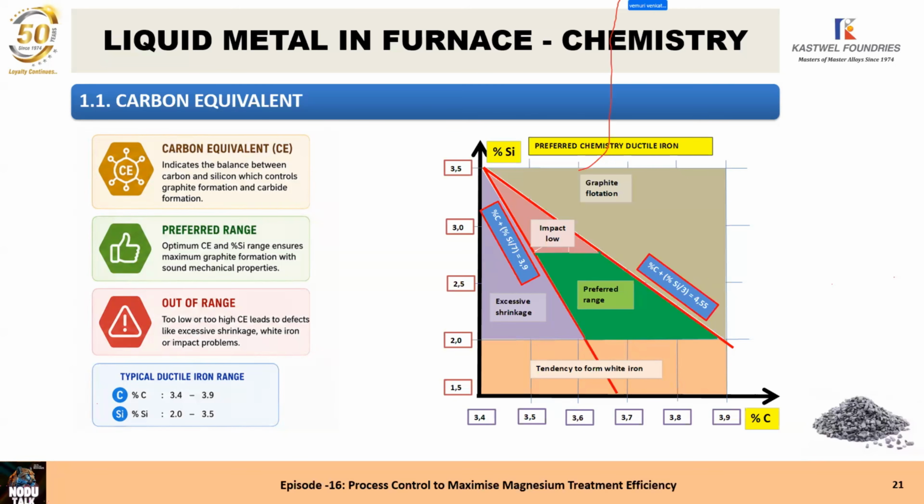Yes, I have heard it. I completely agree, Mr. Basutkar, and I always use the graph. The green zone is the one you should be in. With smaller, thinner castings, you can go a little bit over 4.4, but not that much. Even with big castings, don't go under 4.3. It's a good 4.3 to 4.4. Carbon equivalent should be very good, and check it then with these graphs, which will give you more security that it's okay.